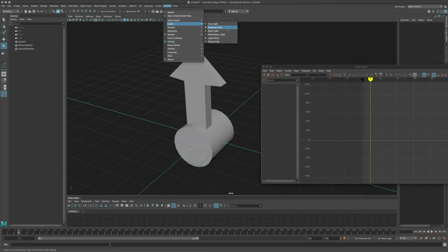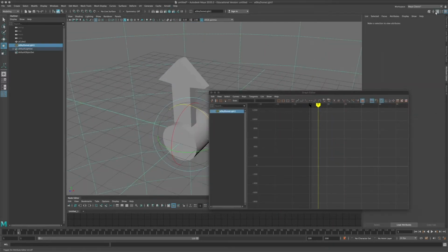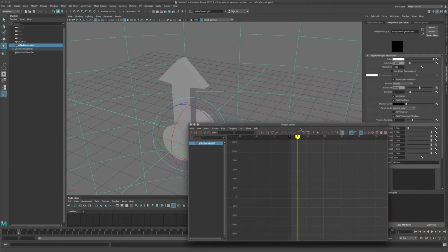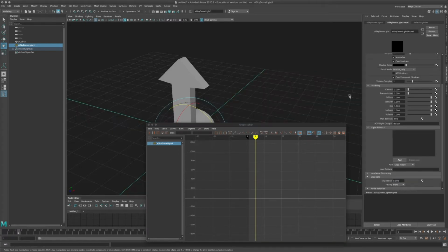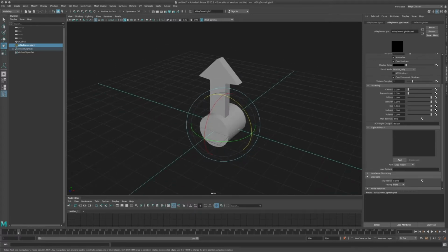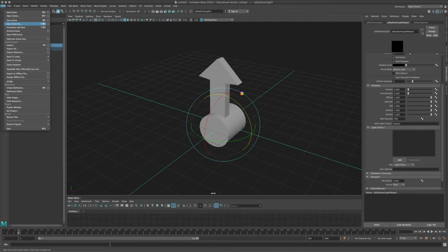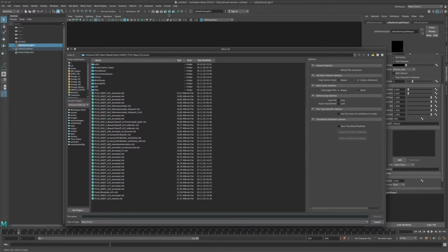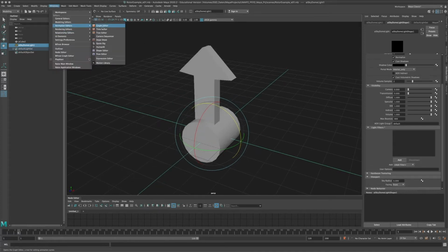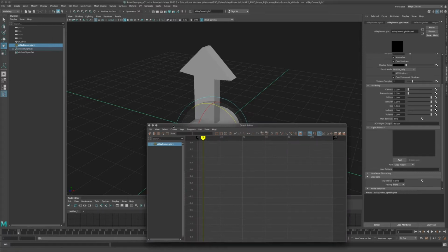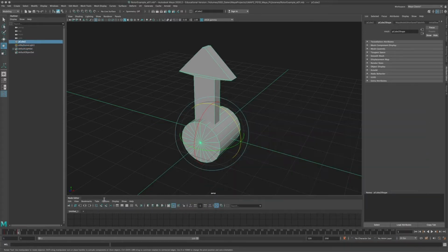And let me just quickly add an Arnold Skydome light here, and I'm gonna hide it in the viewport. Where's the viewport? There's the viewport tab, so make it small so we don't see it, and I'm also gonna hide it in the rendering, so we want to render in front of black because we're just gonna see things a little bit better. I'm just gonna save that here because I will be using a lot of time steps while rendering, so that's rotor example e01.mb, and it shouldn't, but things might crash when running the IPR with that many motion steps. Sometimes it does. So just to make sure that we don't lose much, I'm just going to save that.